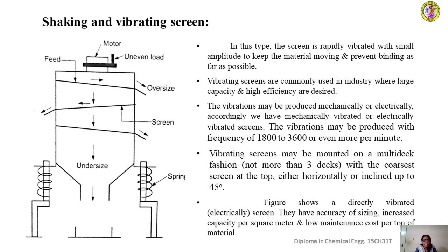Here, each screen in the different decks is mounted with a slight inclination as shown in the figure. The inclination of the screen helps the movement of material over the surface of the screen. So this is all about the construction of a shaking and vibratory screen.